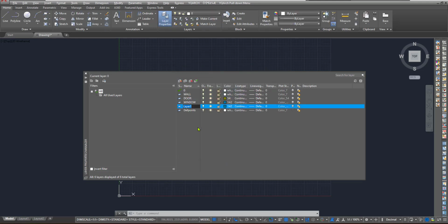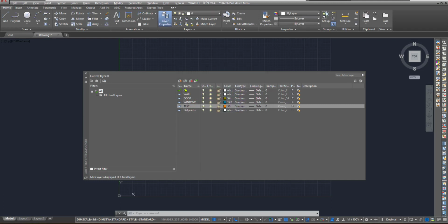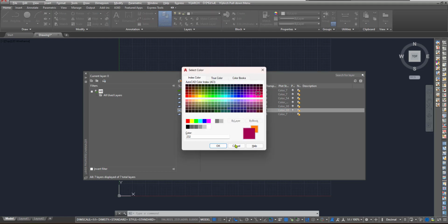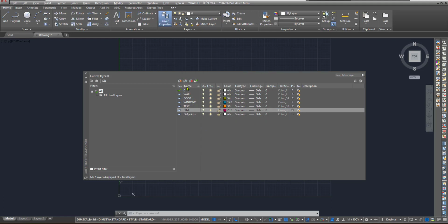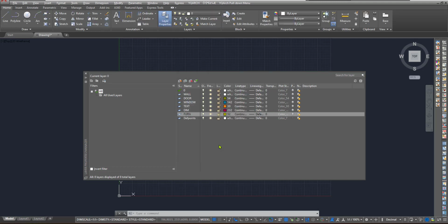Click on the new layer and then you can say text or naming. To give the naming to each room, I create one more layer. Create one more layer for showing the dimension, and apply whichever color you want. And for furniture also I create a new layer. And you can apply the layer colors. Like this you can change the color for the layers.